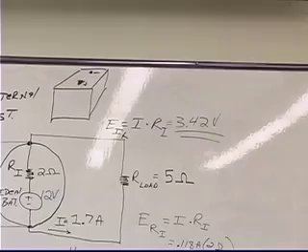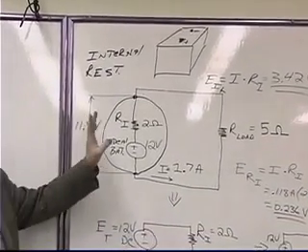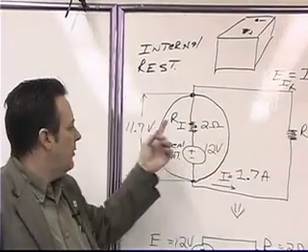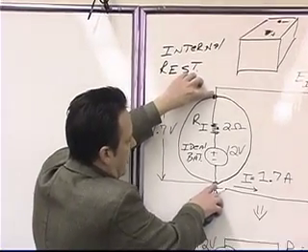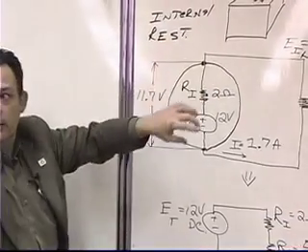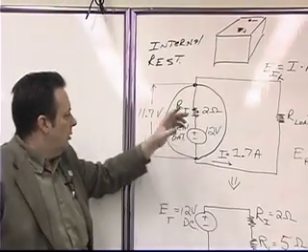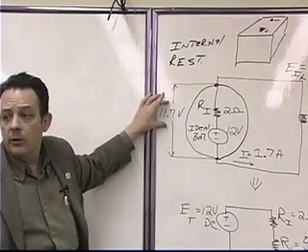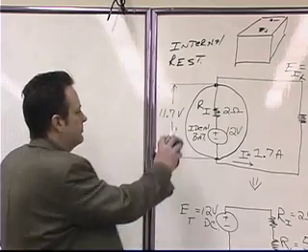That's now 3.42 volts. Okay, now, when we had the first load that was 100 ohms, we found that our usable voltage at the output terminals of our actual source of power, which could be a lead-acid battery from Walmart, had dropped to 11.7 volts. But now it's going to be a different value. What's it going to be now?